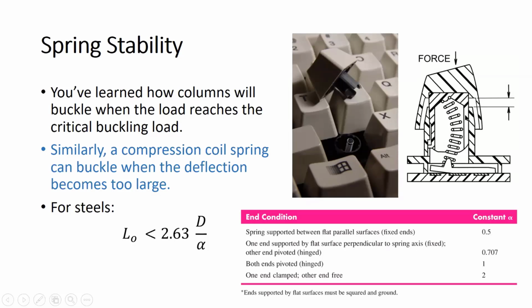For example, a buckling spring is a type of key switch mechanism. So when the key is tapped by the user, it provides auditory and tactile feedback to the user. And also when it buckles, it strikes an electrical contact which registers the key press.